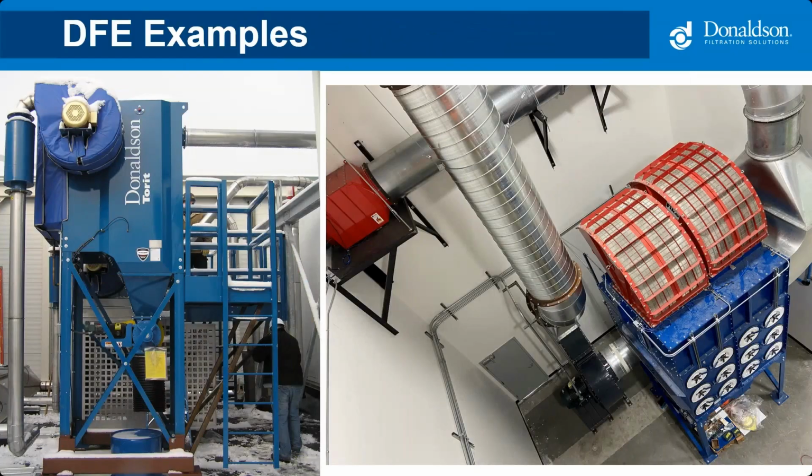Okay. So here are a couple examples of a DFE cartridge. The one on the left is a pharmaceutical facility where the collector's outside. You can see, point out a few different things on here. You've got the quiet cover over the fan housing as well as a silencer. So this is probably in an area where they're being good neighbors here and trying to keep the noise levels down. Also have an airlock on the discharge of the collector there.